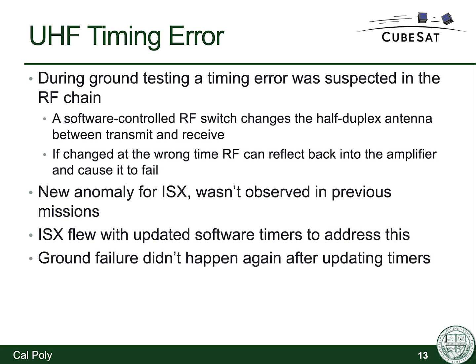We observed amplifiers blowing during our ground testing and development process, and we suspected it was timing related. We went and updated the timers in software. After that, we didn't observe any more amplifiers being blown. So obviously the flight software version for ISX included those timing changes. However, there is no way to rigorously test it and reproduce it. So it's possible that the timer update was still insufficient, even though we didn't observe any more failures on the ground.